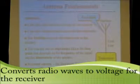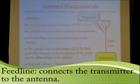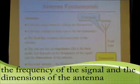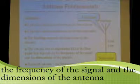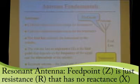So anyway, it converts radio waves to voltage for the receiver, or it converts voltage to radio waves if you're using a transmitter. The feed line is what connects the antenna to the transceiver or transmitter. The antenna has an impedance called Z at the feed point that depends on the frequency of the signal and the dimensions of the antenna. Remember, this feed point Z is just resistance. It has no reactance. Actually, there are some situations under which you can have reactance. You don't want that, but it can happen. But typically, you want the feed point to be pure resistance.